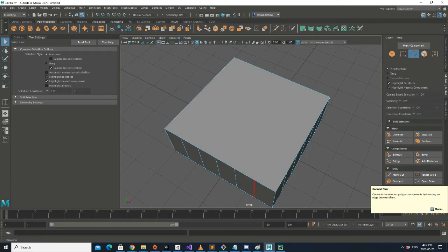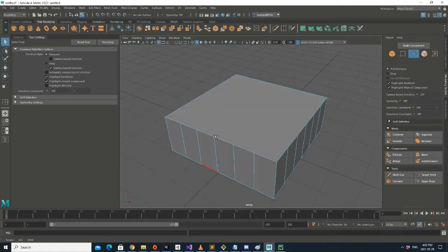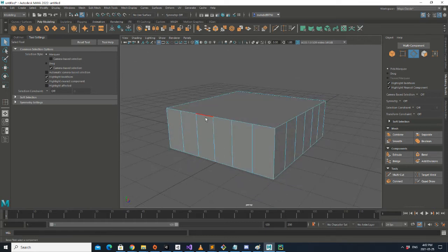Sorry for the interruption, but what's the logic behind that? Why are you doing this? Yeah, so the faces should only have 4 or 3 vertices. More than that is really hard to modify, because faces have just one normal, and when you are trying to move some vertices up or down, or change their position, you want your face to be flat.